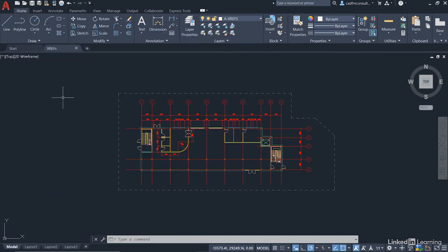Now, these XREFs are very useful because if you've got a really large, complex file that you want to paperclip to your existing drawing, the good thing is the file size is only about 10% of the actual file size when you XREF it in. So you're not making your host drawing a really big file. You're only using about 10% of the reference file, which makes life a lot easier for file size when you're manipulating your host drawings and your external reference drawings as well.